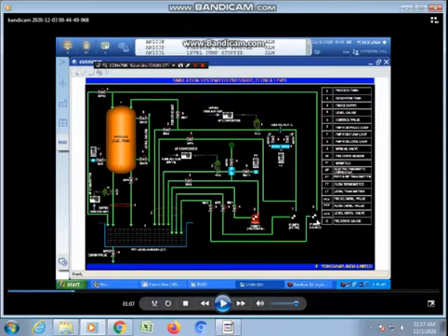This level pump will be working, and it is feeding the water to a stainless steel water tank. There is a safety valve which will bypass the water so that we do not affect our pump. Then from the water tank the level is taken as a signal through this differential pressure transmitter, that is a level transmitter connected in here.